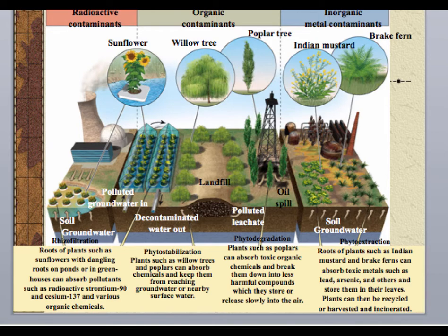So let's look at how we get these hazardous materials to be less hazardous substances. The first one is going to be biological methods. The first one is your bioremediation. This is using bacteria or enzymes, and those are going to help destroy the toxic and hazardous waste or convert them into more benign substances. The second one is going to be phytoremediation, and this is using a natural or genetically modified plant to absorb and filter and remove those contaminants from the polluted soil and water.